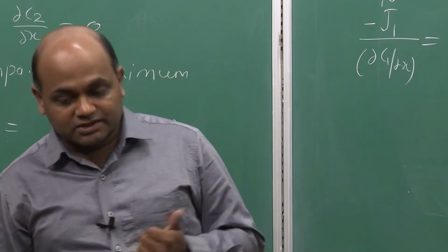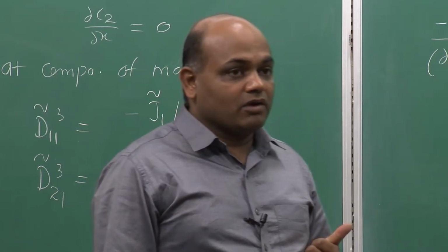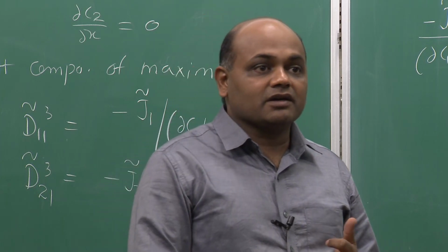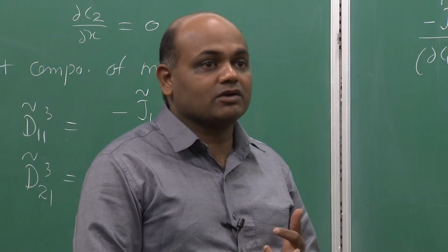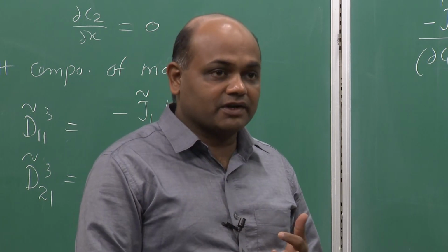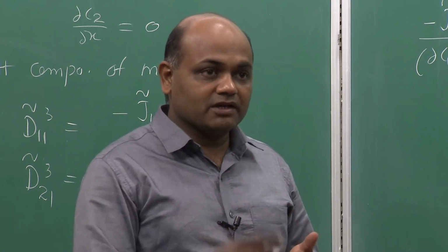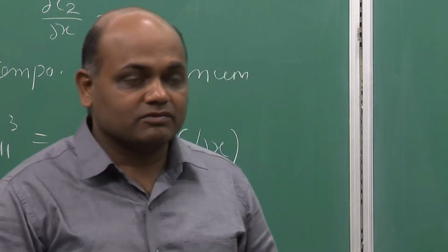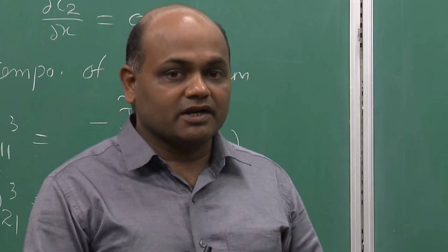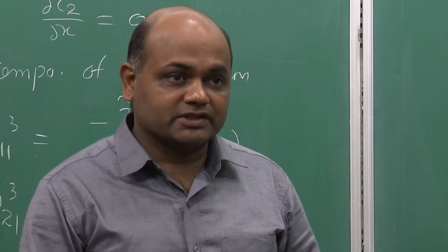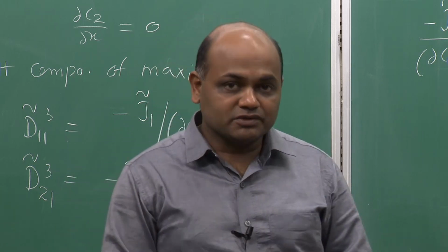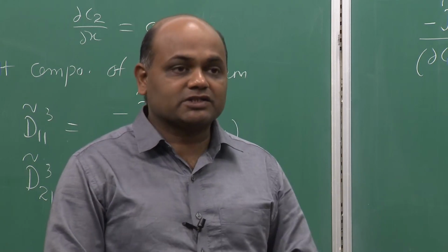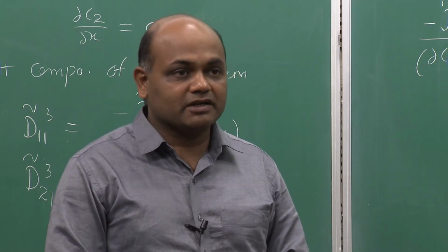Again, one assumption is that all the components which are supposed to be invariant will not develop any uphill diffusion region, which means they will not exhibit significant diffusional interactions from the other components. Okay. So, these are some of the experimental techniques which we can use for determination of interdiffusion coefficients in multi-component systems. In the next class, I will show you some specific examples from the literature in which such estimation of interdiffusion coefficients has been reported.